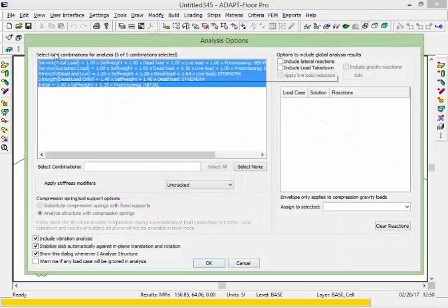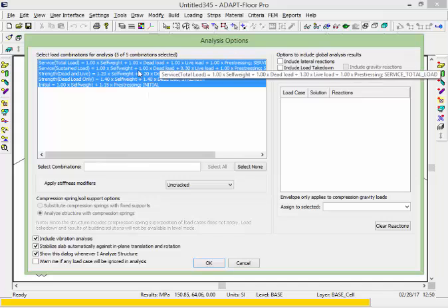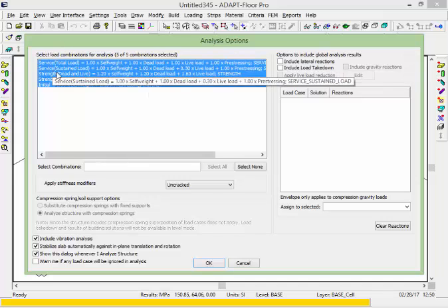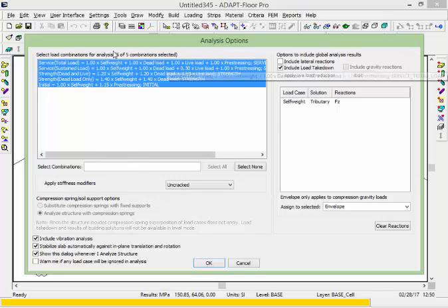We're going to analyze this just for the default load combinations, which are gravity oriented. And I'm going to use the option for include load takedown. This applies to gravity loads, and the gravity load takedown that we're going to introduce shows us that we have only self-weight. It doesn't show the loads that were imported from Etabs, and the reason for that is the combinations that we have defaulted to include the predefined load case names in Builder. We have to add the load case names that stem from Etabs.